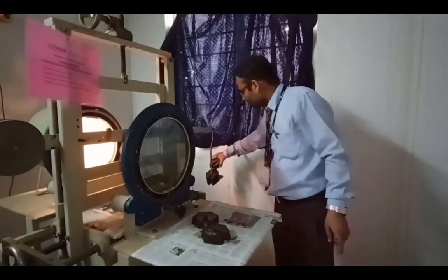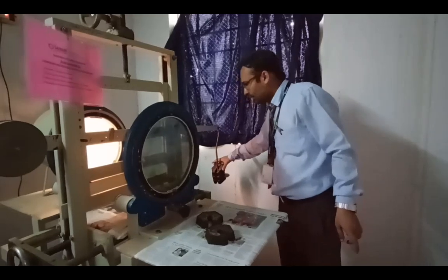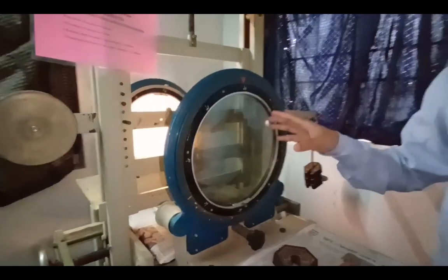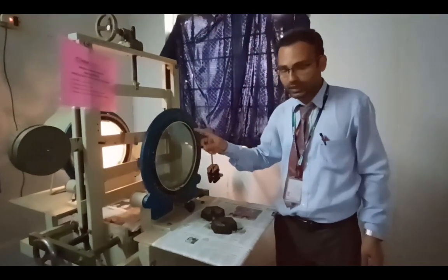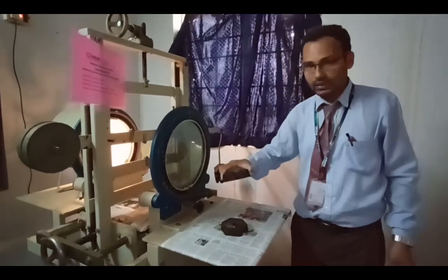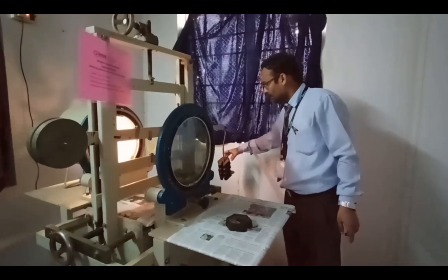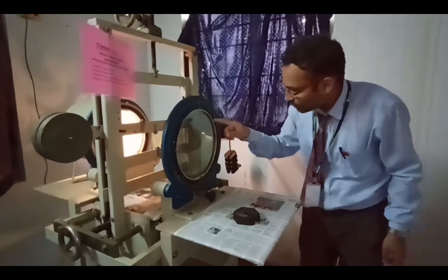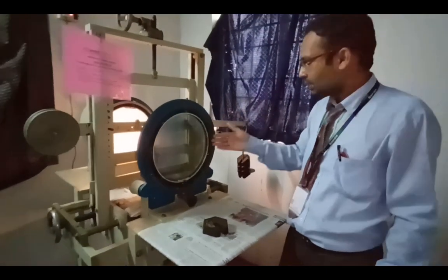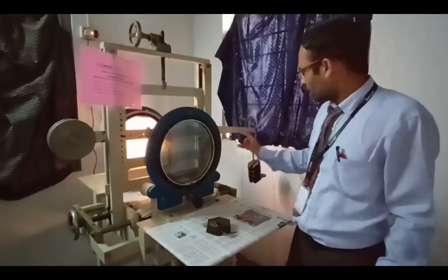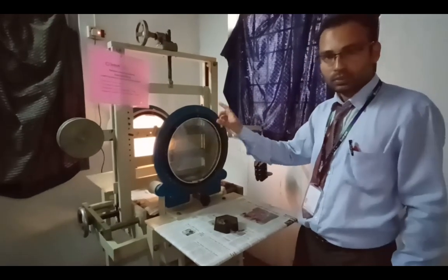Similarly, if you keep 3 kg of load and hang it here, again observe through the circular polariscope, you are going to get 3 fringes. At 2 kg you get 2 fringes, at 3 kg you get 3, and again at 4 kg of load you get 4 fringes through the analyzer. Like this you have to repeat this experiment for 4 or 5 readings, and note down in the tabular column the number of fringes at each load, starting from 1 kg.